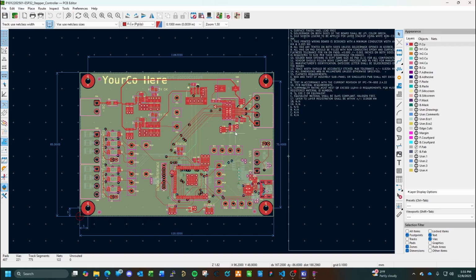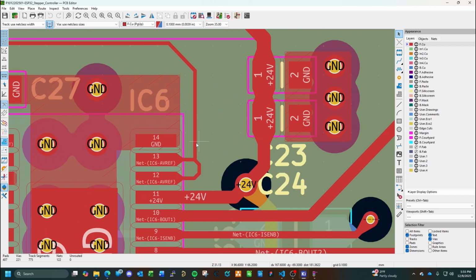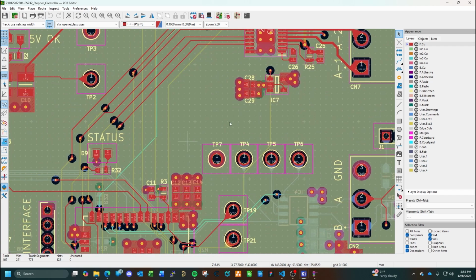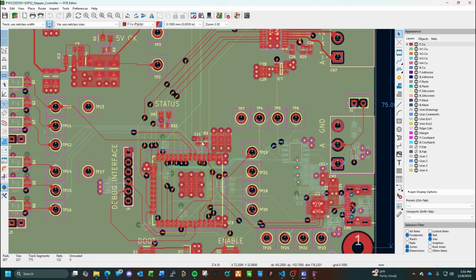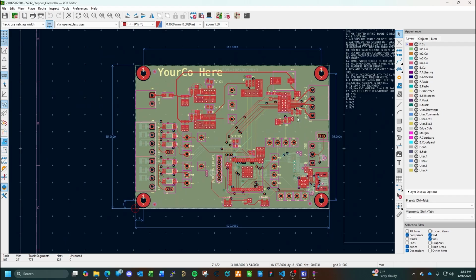And then the distance between pads in the footprint, there's nothing we can do about it. That's the way the parts are designed, their designated pad spacing and size. We just have to ignore those rules and be okay with it. So we did as much verification as we could here.